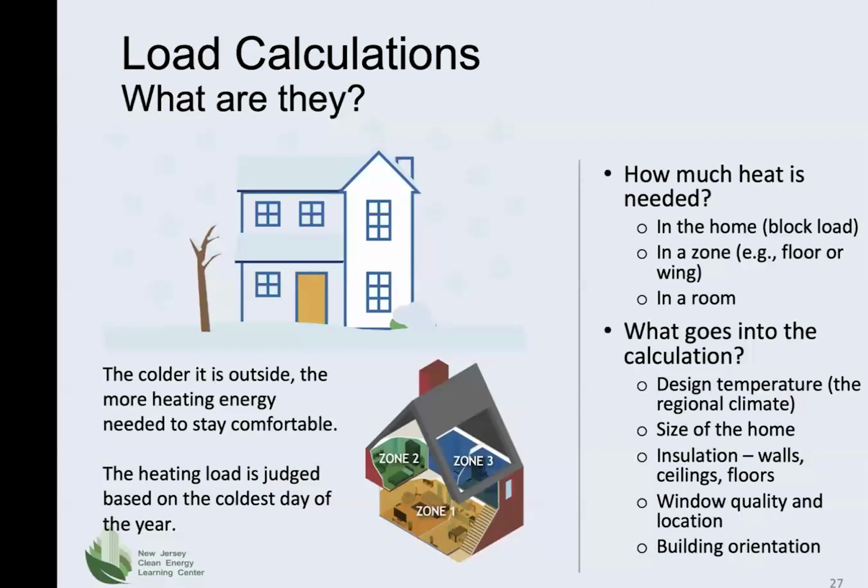To calculate a home's annual heating load, binned weather data is used to determine how much heat is required to heat a home for an entire year. Load calculations can be performed for an entire house or various parts of the house. When a thermal load is calculated for an entire house, it is referred to as a "block load" calculation. Alternatively, loads can be calculated for a zone of the house or on a room-by-room basis.